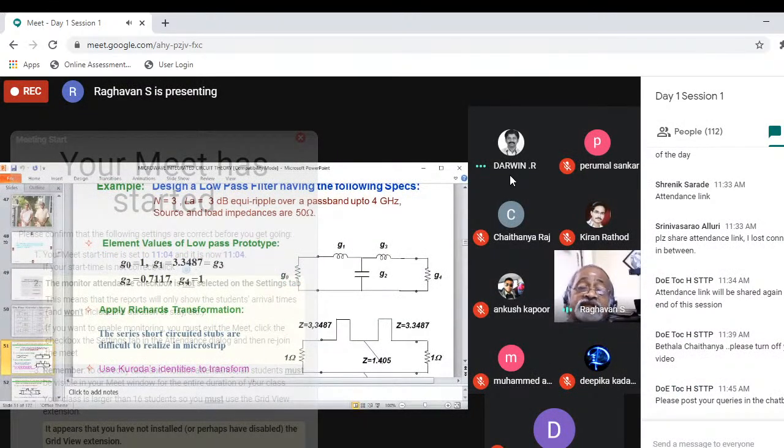as a shorted transmission line, the capacitor as an open transmission line. That way you represent it in the distributed way. Then if you want to represent the series only into parallel or parallel only into series, you just add a unit element. By adding a unit element, the property will not get changed. So that way you can have the component fully series or fully parallel.